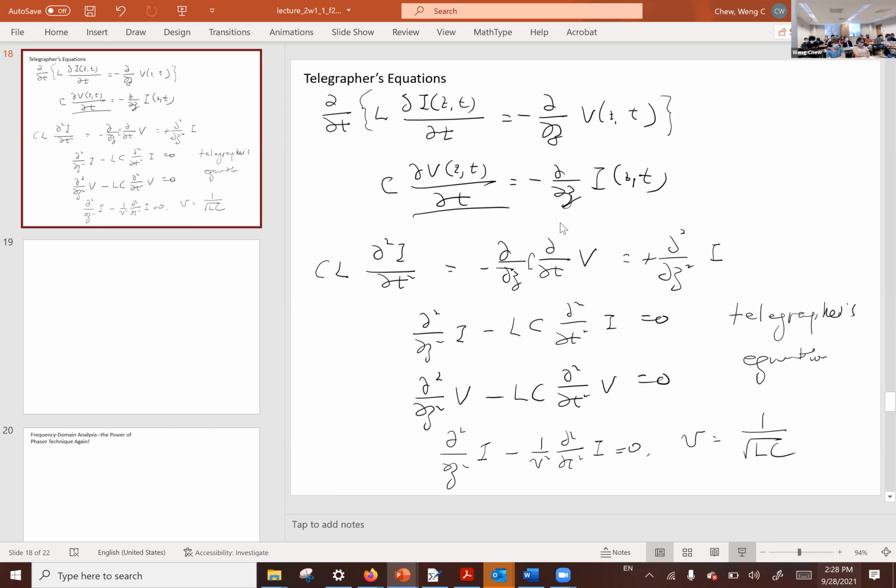So with the recognition, remember this: impedance of free space. Because this is using Maxwell's equations, there is also a relationship between V and I in the transmission line. That relationship is not called intrinsic impedance anymore. The E and H are not related. The relationship is called the characteristic impedance of the transmission line.